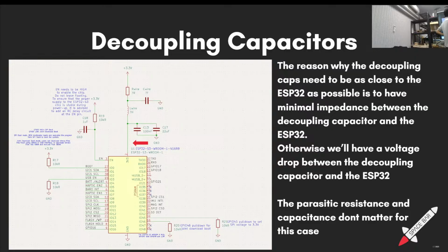So I can put a bulk decoupling capacitor here, and this goes to ground, right? This is a huge decoupling capacitor for the whole chip. But the problem is I've also got this line and this line and this line and this line. These all have their own inductances, correct? So I have a tiny capacitor on each one of them, which absorbs the voltage drop for long enough until the impedance of this is overcome by this. Does that make sense? You match it to the one over there, just to be sure.